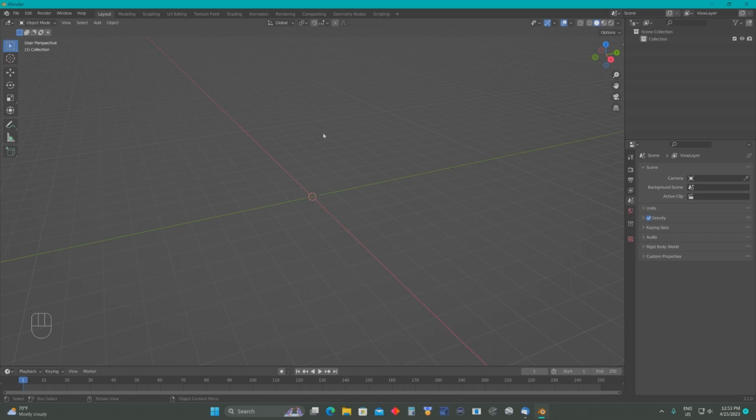So to begin with, in order to look around here, you're going to want to hold the middle button of your mouse down, and while you're holding it, you can move the mouse and look around like this. Okay. If you want to move the object around on the screen, go over here where it's got a picture of a hand, and click on it.